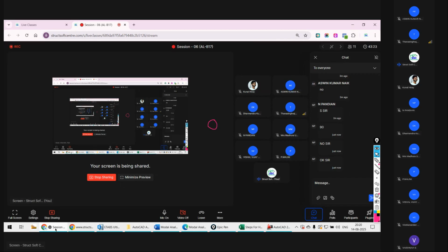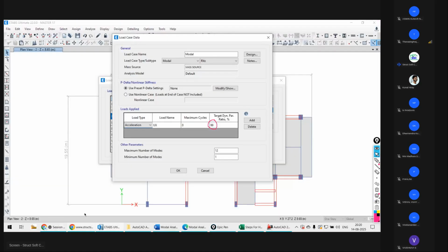अगर आपको किसी स्ट्रक्चर में 100% मास पार्टिसिपेशन मिल रहा है तो it's a good thing या bad thing? That's a good thing. Okay, that is the ideal condition. वही तो हम लोग चाहते हैं. So it is 99%. Okay, now for the X direction I would like to add one more, for the acceleration in the Y direction, again 99%, right, for X and Y direction. And now the maximum number of modes.